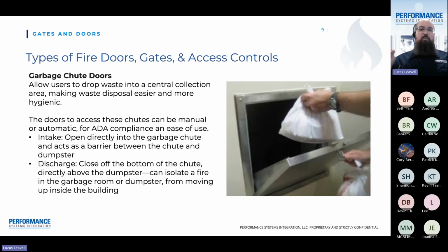They don't call a bad situation a dumpster fire for no reason. Dumpsters are both sources of fuel and just accelerants in the form of anything that someone has disposed down the chute. If a fire does start down there, it can very rapidly and without much warning get out of control. And if it has a garbage chute directly above it, that is a chimney for it. That means it will allow the heat to move upward and draw oxygen at the bottom, allowing the fire to get bigger and bigger and bigger.